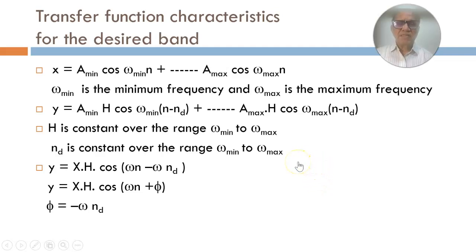Alright, so in this session we have defined what a filter is, and in general we have seen the relationship between the coefficients of the filter and the impulse response, that they are the same. And then we have studied the basics of the transfer function, and we have said what should be the nature of the transfer function so that there is no distortion of the signal in the band of interest.